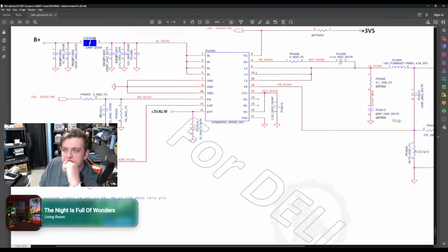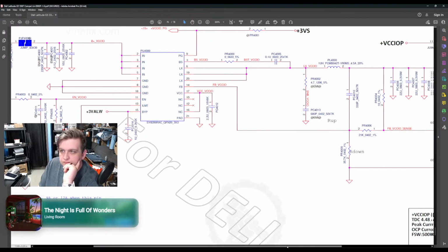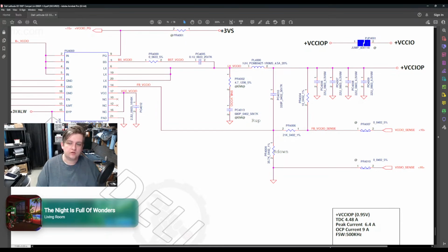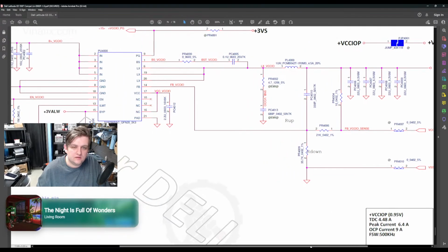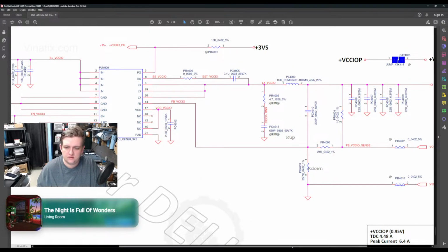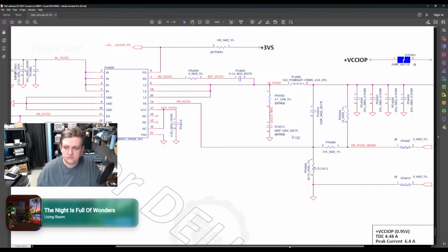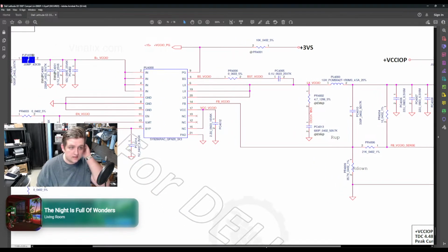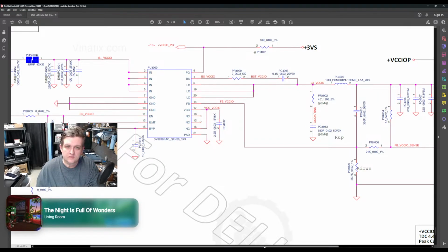Okay, so pins 19, 20. Right now I'm trying to figure out what killed it. I think it was the charger, because as soon as I plugged in his charger cord, it made this weird sound. I'll see if I can replicate it before I replace the chip, because I'm definitely not going to plug that charger back in until I tear down the charger power supply.